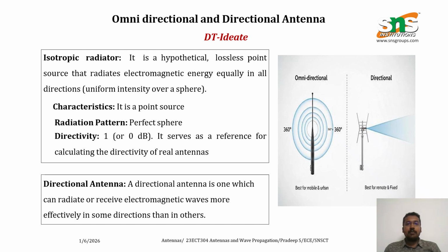In a small center-fed dipole, charges reach a maximum during the first quarter of the period. Lines of force travel outwardly a radial distance of lambda by 4 during this time. During the next quarter period, the original lines travel an additional lambda by 4 while opposite charges are induced at the conductor. As the net charge on the antenna becomes zero, the lines of force are forced to unite and form closed loops.